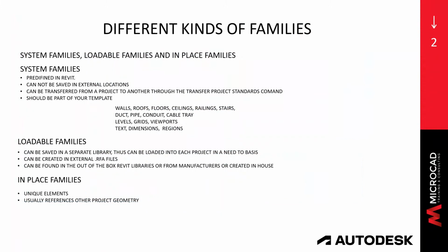System families are predefined in Revit. They cannot be saved in external locations. They can be transferred from one project to another through the transfer project standards command. Most of them should be part of the templates.